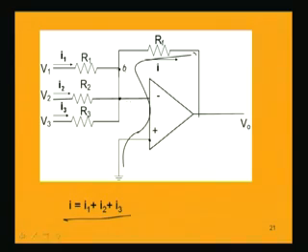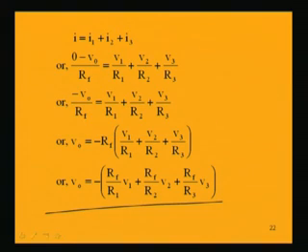If we look here, all the voltages are connected to the inverting terminal. So, obviously, the minus sign will come as the output will be out of phase, or 180 degrees out of phase. But if we look into the bracketed expression, it is like a summer, V1, V2 and V3 are summed up, of course, with a scaling by the resistances, meaning V1 will be multiplied by the ratio Rf by R1.